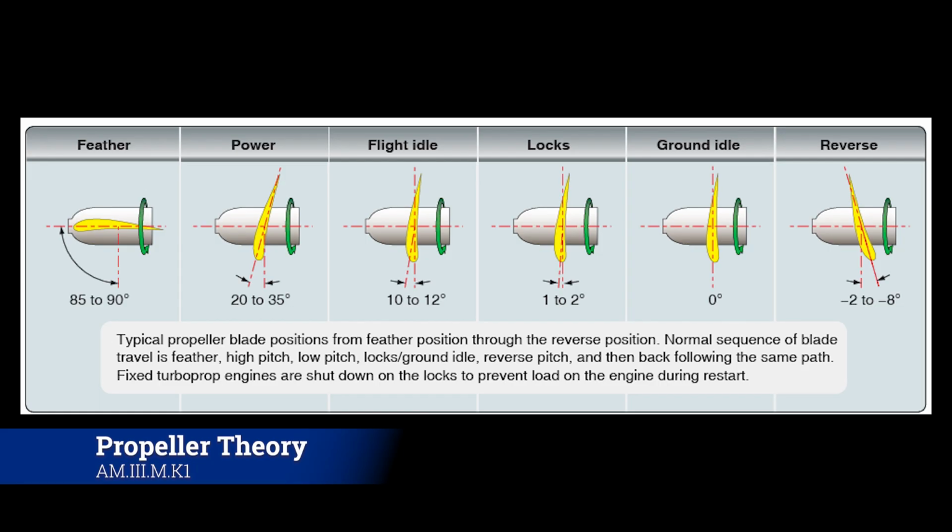And so you'll see a lot of this on high-end turboprops like your King Airs, and so on and so forth. Whenever they go to land to reduce their landing roll, they'll throw the prop into what they call beta. So they'll put it in reverse, and it'll turn around and slow the plane down a lot faster, and therefore reduce your landing roll. The Quest Kodiak has a really aggressive beta range, and you can set the plane up so that as soon as it lands, once it sees weight on gear, it kicks that beta mode in, so it really stops the plane.